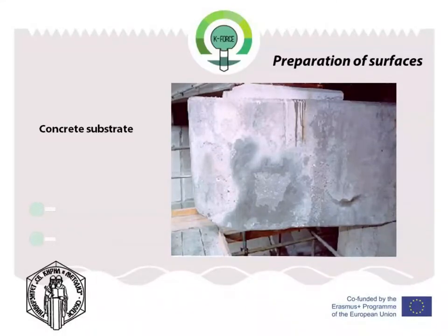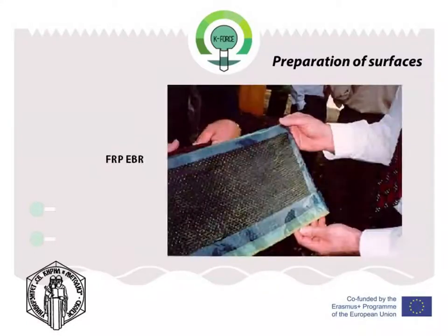The concrete surface shall be marked where the externally bonded FRP reinforcement has to be applied. Strips, laminates, or fabrics should be supplied to site at the specified width and cut to the necessary length as specified on the design drawings. They should be free from any contamination like oil, dust, carbon dust.